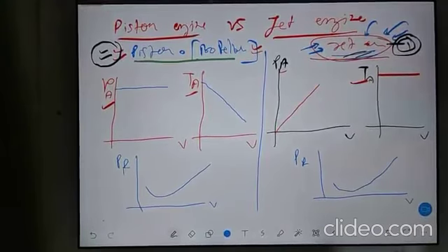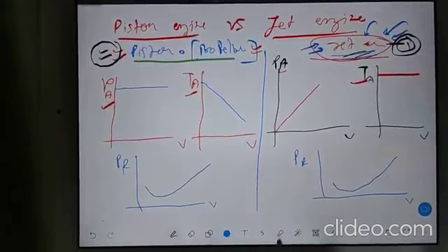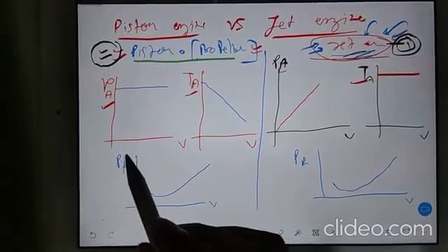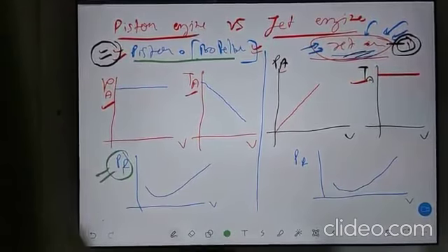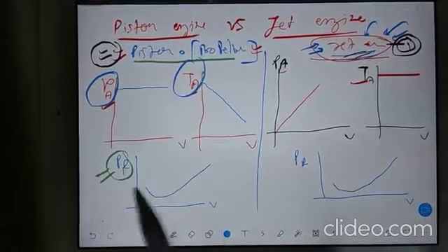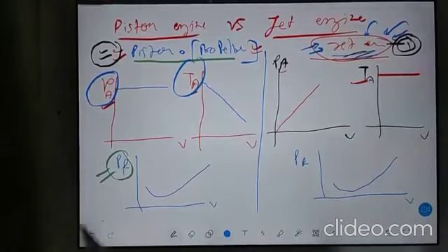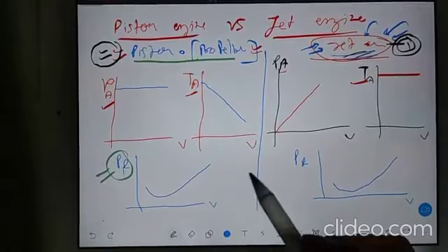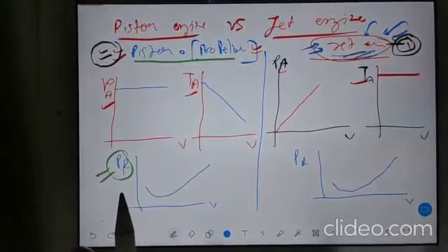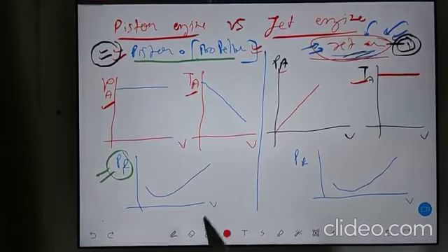Power required is almost the same, because power required depends on outer phenomena, not engine phenomena. Try to understand what I'm saying. Power required is because of drag and all. If you don't have drag, you have no need of power. Because you have drag, you need thrust and power to overcome it. But availability is the engine phenomenon, like what kind of engine you are using: General Electric, Rolls Royce. These are the companies, and in future you will be getting jobs in these companies.